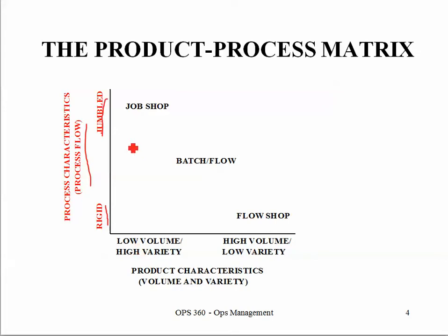And that would be the case where every product that you make, or at least lots of the products that you make, have a different flow or sequence of operations needed to make them. So take an extreme example. If you're making different types of parts, you might have a sequence for one type of part that first starts out in grinding, then goes to milling, then goes back to grinding, then goes to milling, and then goes to paint.